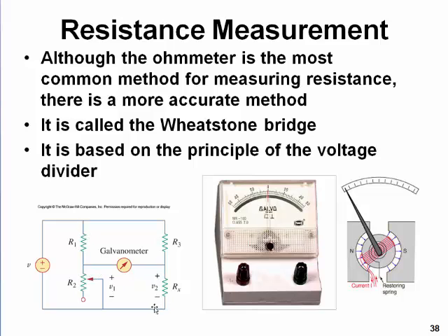When you get this Wheatstone bridge balanced, then you'll have no current through the galvanometer. And that's how you can use this configuration to determine an unknown resistance. So let me look at it from a practical and simple way to analyze the circuit. I'm sorry I don't have the circuit pasted in here in advance, but I think we can work with it. So I'm going to draw a circuit.